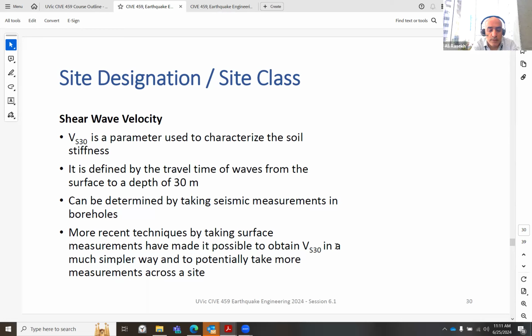However, now good measurements can be done on surface wave velocity, in a way, ambient waves, which are caused by very small vibrations or daily super small earthquakes. Some companies are expert in that. They can do it at less cost without having borehole tests.